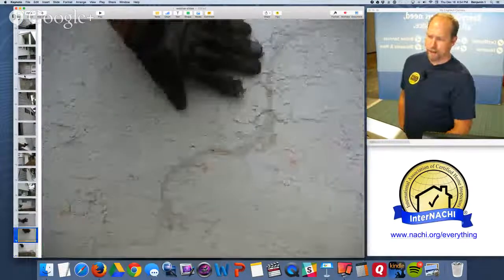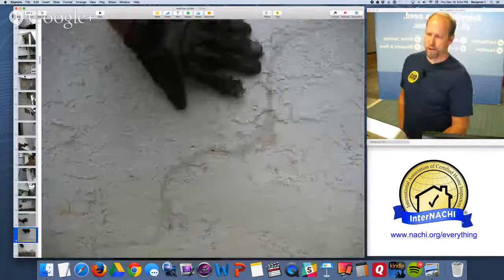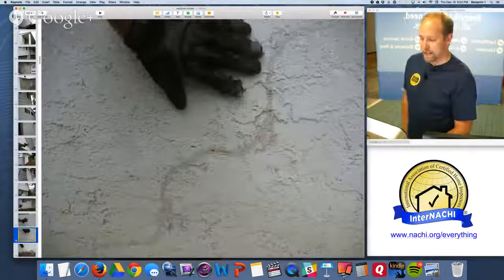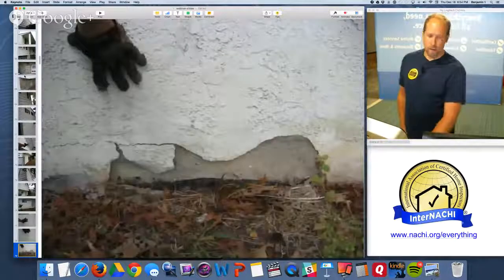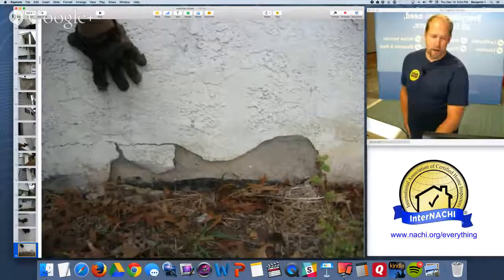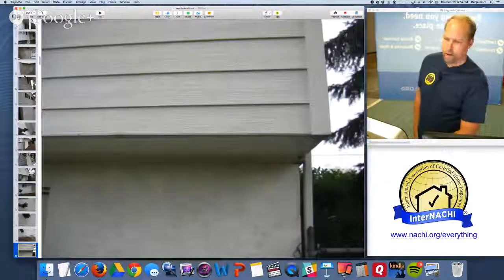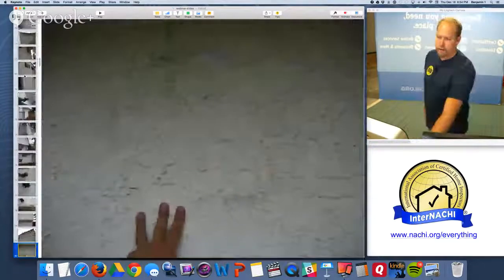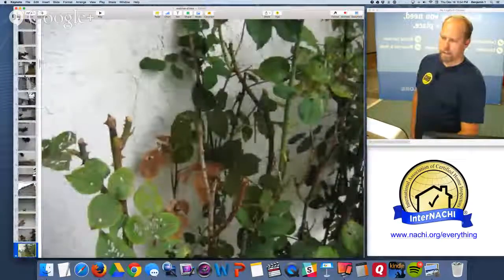It's not patched up very well. I like to patch it with like material. This was patched with white silicone. It never works really well. It's aesthetically unpleasing. Some of the parging near the bottom is falling off, kind of minor. The structure looks great. More cracking, pretty minor.